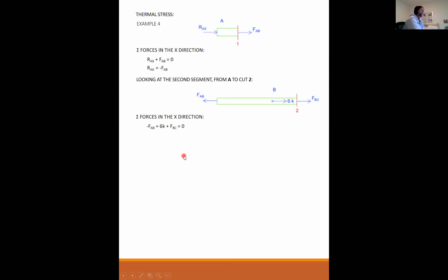I have two equations for two unknowns. I have the first equation that came from compatibility. I have the second equation that comes from stability or equilibrium. Two equations, two unknowns. Now I can solve my problem. Yes, I can substitute, so that's exactly what I'm going to do. I substitute for FAB this equation that I found for FAB, and the only variable in this kind of messy thing here is FBC. So I have only one variable in this whole equation, FBC, which means I can solve the problem.